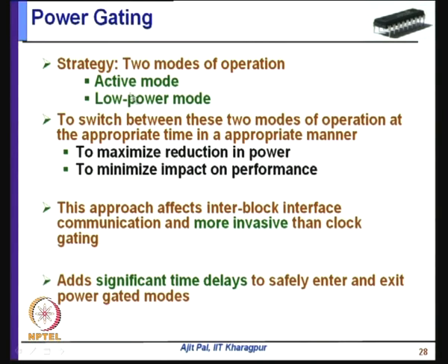And power gating can be done, which is known as MTCMOS. Again, you have got two modes, active mode and low power mode. In active mode your performance is better, and in low power mode there is a significant reduction in power dissipation.